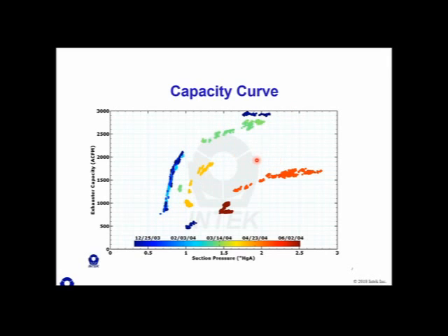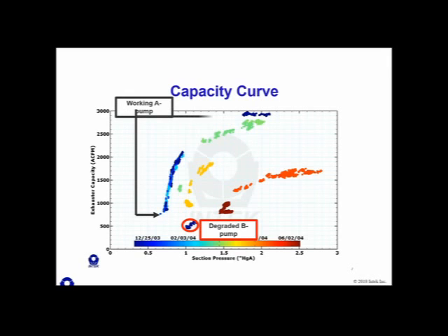So you can plot this data up and monitor it over time, and you'll get your pump curves. You can tell if your pump is performing as it should be over many different times of the year, and compare it to manufacturer specifications. A very, very useful plot for monitoring your vacuum pump performance is CFM versus pressure. There's the poorly operating pump 62, and there's your working pump 61. And there's your different curves for the different temperature of cooling water or seal water, essentially.